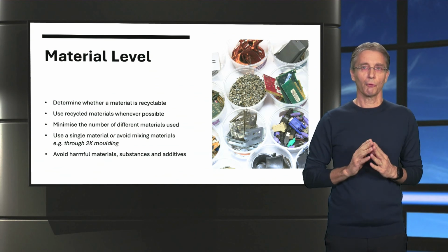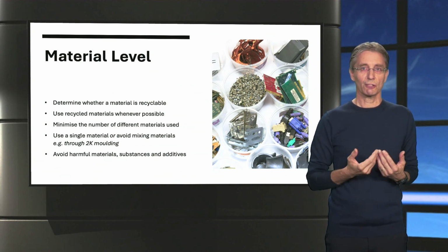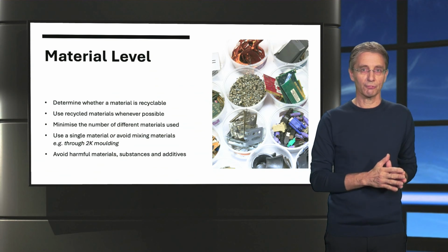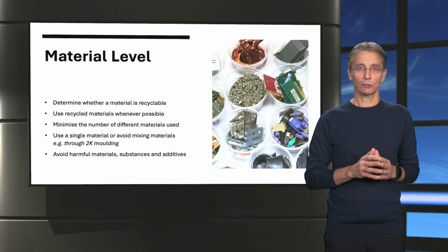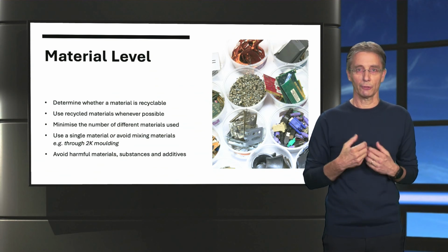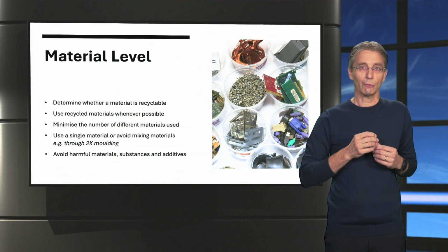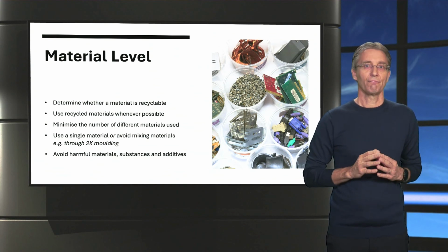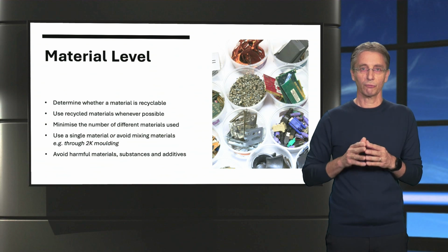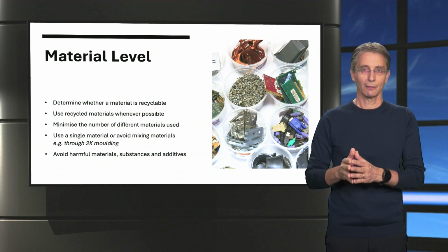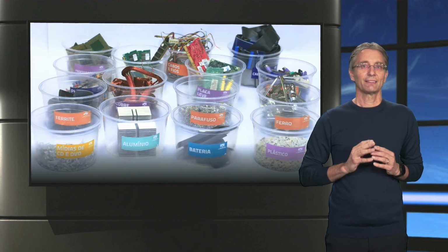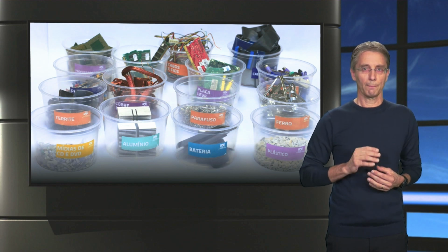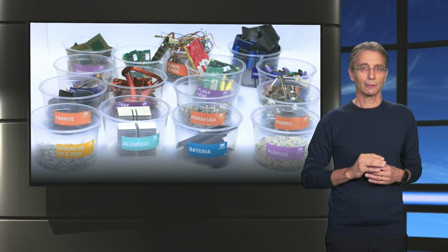Furthermore, avoid using materials, substances or additives that are harmful to the environment and human health. These are the substances of very high concern defined by the European Union's REACH regulation, and those included on the SIN list, which may prevent the material from being recycled in the future. Taking these considerations into account during the design process will improve the recyclability of your product.